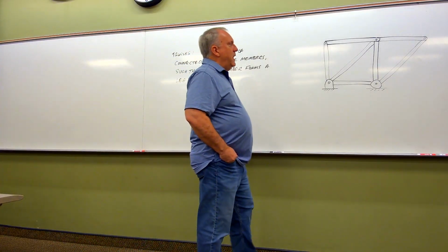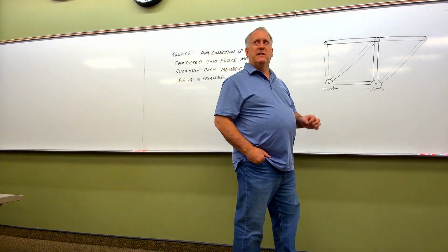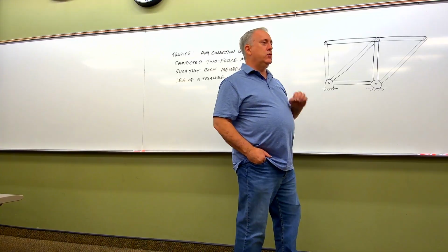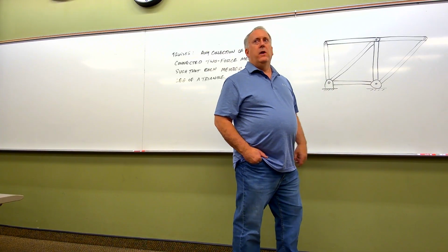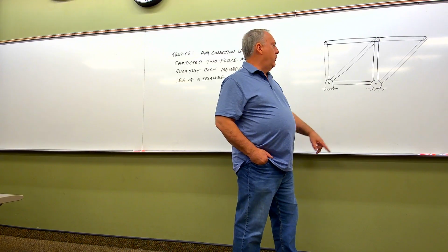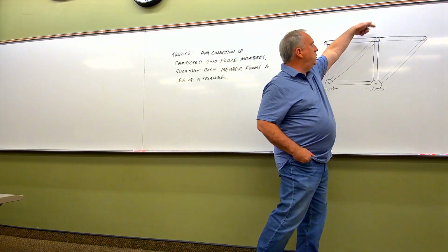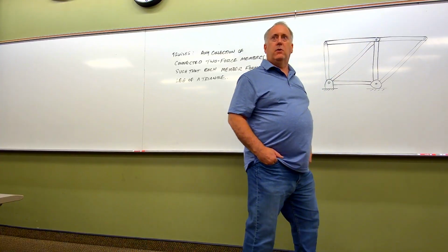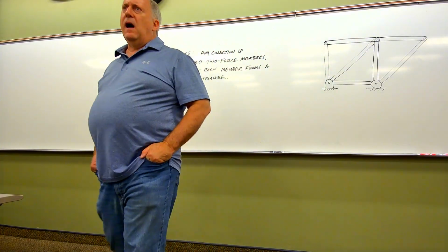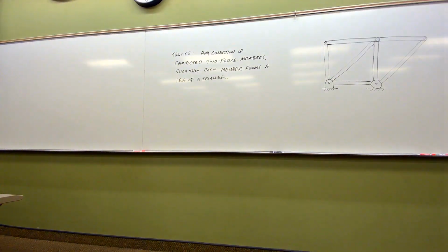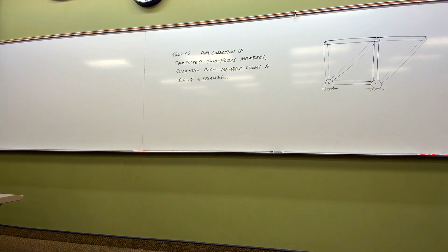So usually, every time we show trusses supported, it's going to look like this. There's going to be a pin, there's going to be a roller. Now, there can be variants of this. For example, we might have a pin and maybe some tension member, like a cable, holding up the truss. That's perfectly fine too. But there's a reason behind showing this kind of a support system, even though it isn't exactly what we would expect a real life support system to look like, and it is this.